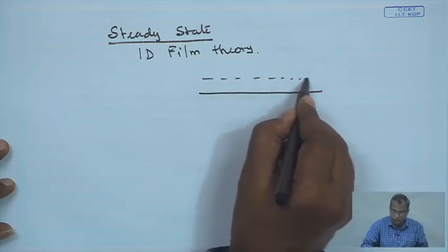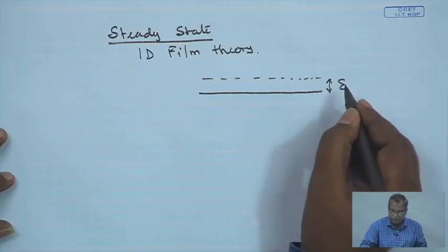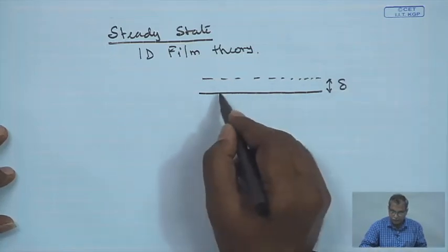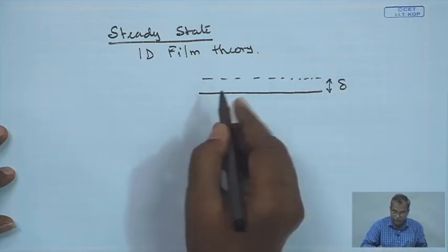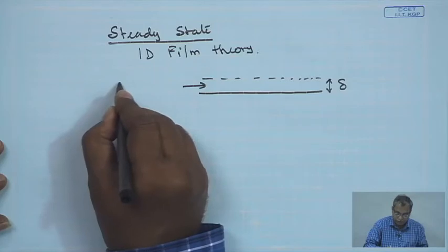that we considered in the case of osmotic pressure controlled filtration. We assume a constant film of solutes of thickness delta is formed over the membrane surface, and it has a constant solute concentration within the gel.